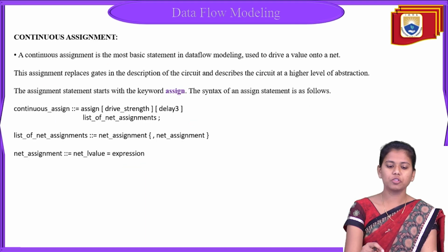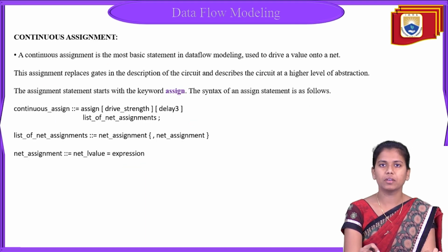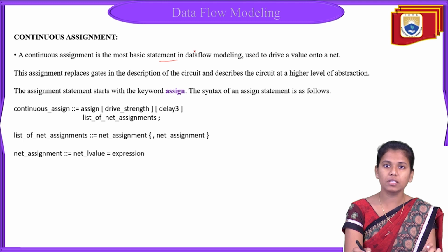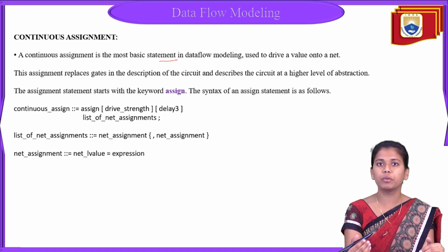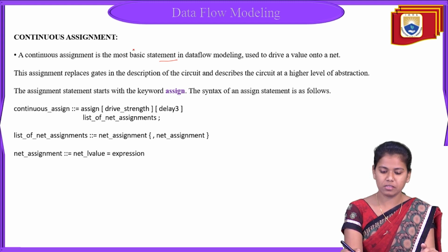Okay, coming to the continuous assignment. What does this continuous assignment talk about? It is the most basic statement in data flow. As we are discussing, the topic for today is data flow modeling. We will see how the program can be written in the form of continuous assignment. This continuous assignment is the most basic statement in data flow modeling. It is used to drive a value onto a net.